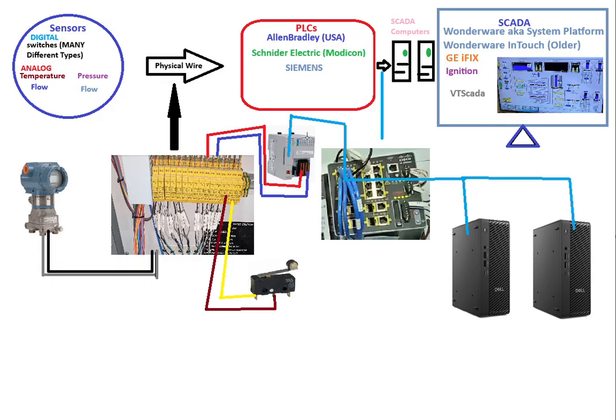After that, your PLC basically turns these raw signals via embedded circuits and integrated circuits into computer code or object oriented code that's spit out over Ethernet, but usually it's using proprietary encapsulation or layering on the Ethernet to give it the manufacturer specific Ethernet protocol that hits a network switch, goes out on a plant wide network, and those are eventually hooked to SCADA servers.